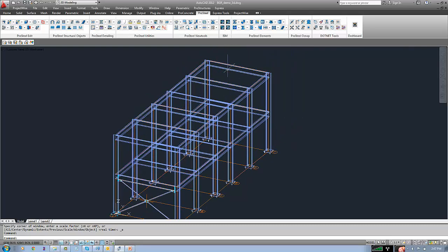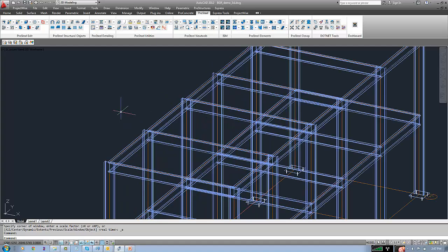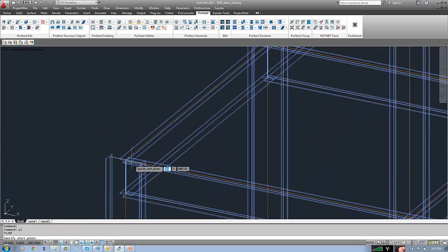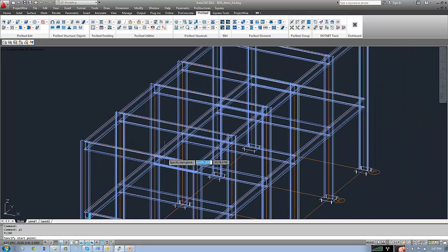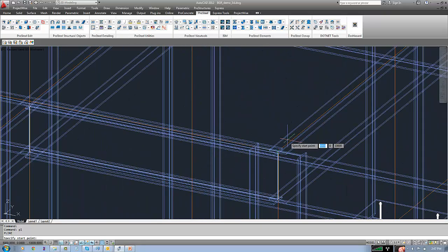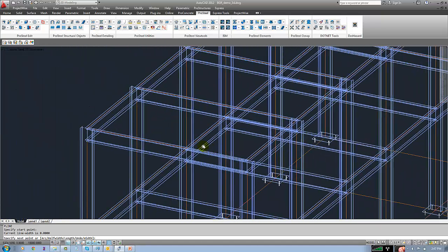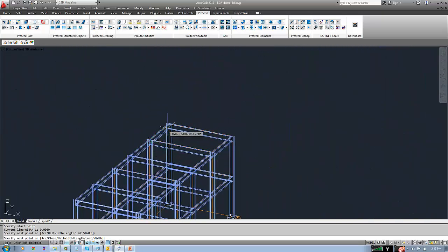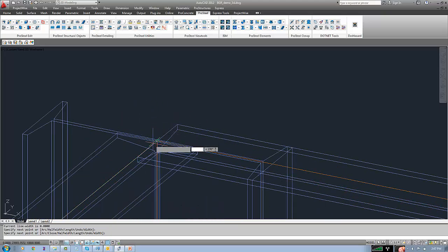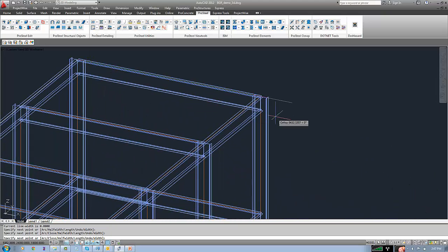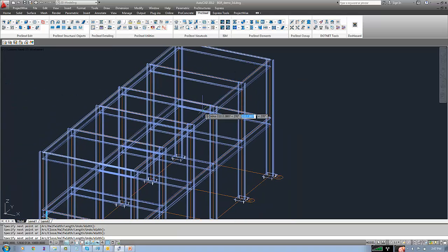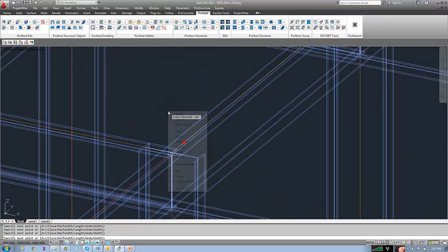Here I am going to place a handrail. So to create a handrail, you need to draw the polyline where exactly you would like to place the handrail. So I will start the line, say from here to here, 0.3, 0.4, and some point around, say maybe here.